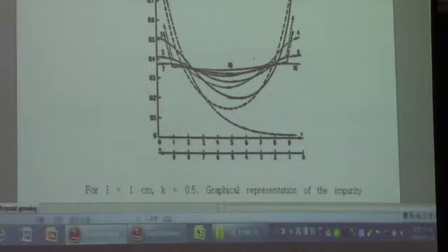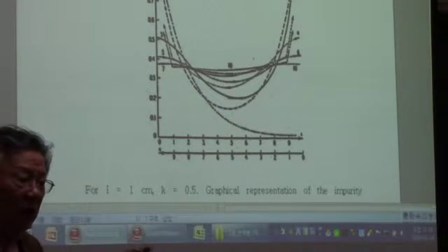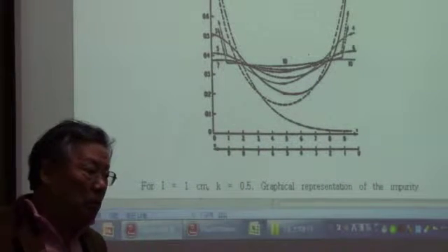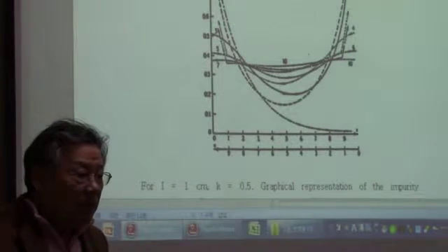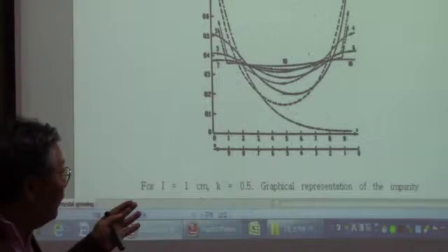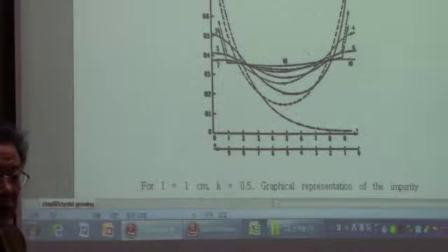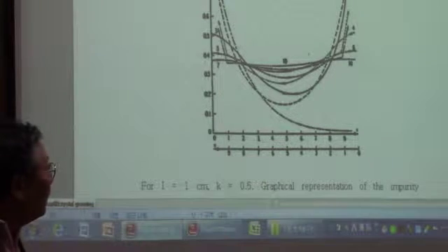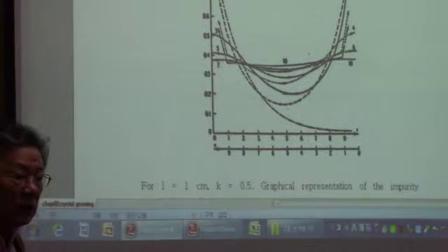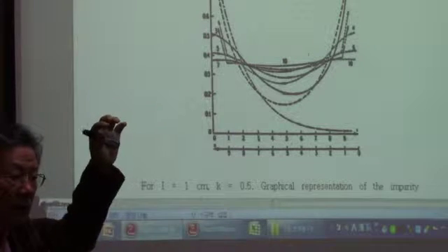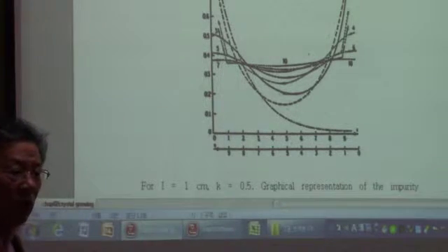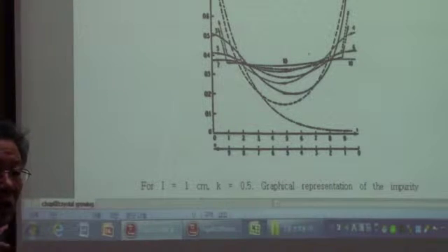So obviously you can see that compared to the Czochralski technique, the float zone technique is not that advantageous to make big wafers. But you just repeat the scan, then you have a flat distribution of the dopants along the length of the single crystal in the float zone technique, no matter what the K naught value is.